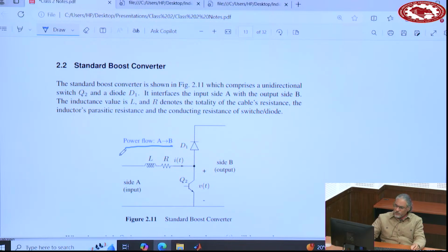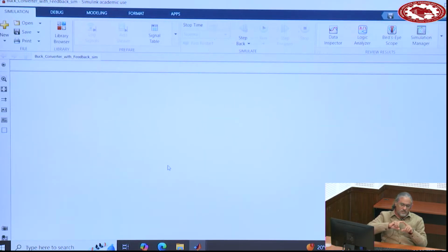Now, how does this work? If you turn on this switch, this becomes a short circuit. The voltage here becomes 0, and then you have voltage VA. So if VA is positive, then a current will flow here. So that's the first condition, VA being positive. The current will flow here, and that current will ramp up linearly, will keep going up. Like yesterday we said, if you don't stop it at some point, it's going to damage the switch. So at some point, what we do,